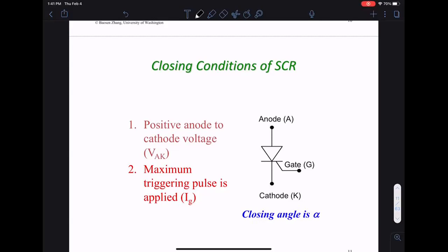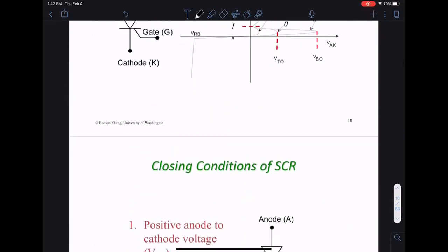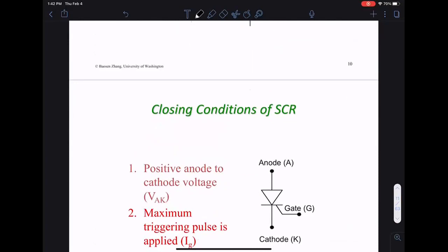We like the SCR quite a bit in power applications, for the precise reason you have seen in type 1 and type 2 turbines. This triggering angle gives you a control variable, and this control variable can dynamically control something like the outer resistance. That's why we use the SCR, a lot of the time. Basically it's a combination of a diode and a bipolar transistor. You take a diode, squash a bipolar transistor into it, and you get an SCR. That's sort of how you make this type of thing.